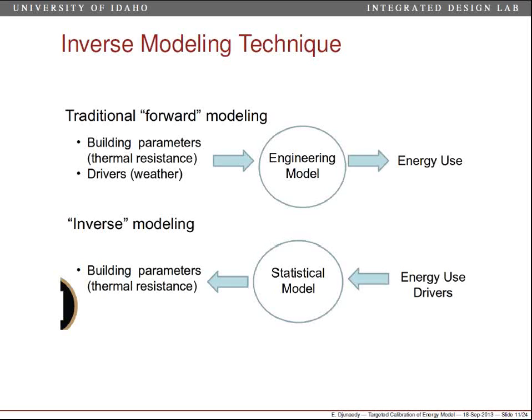Typically, inverse modeling technique is not used in conjunction with an energy model, but separately as a way to quantify savings. So this initial project, the so-called measurement and verification project that we do for Idaho Power, comes from this area. We want to quantify the savings. Idaho Power has paid this much incentive for this EEM. We go to the building, we measure, and we use this method to quantify the savings. Per year, this many kilowatt hours is the savings.